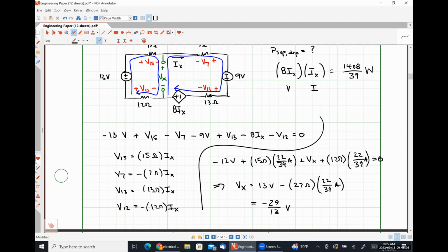Oh, so why did I choose that way? To make it confusing. To force you to realize that sometimes Ohm's law is going to require a negative sign. So when you do these by yourself, the obvious way to set a circuit up and introduce the least number of negative signs would be to make it so that the current is flowing into the positive polarity terminal whenever possible. But because I am mean, I chose some of them of the opposite polarity to try to trick you guys.